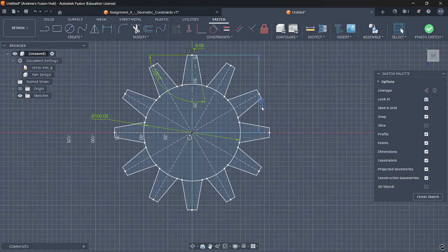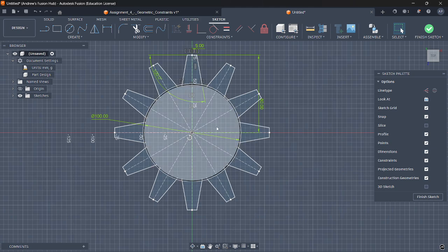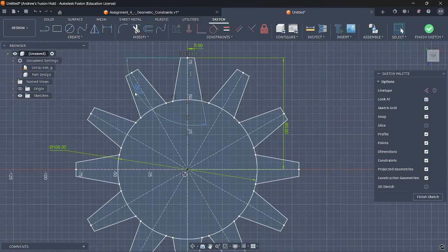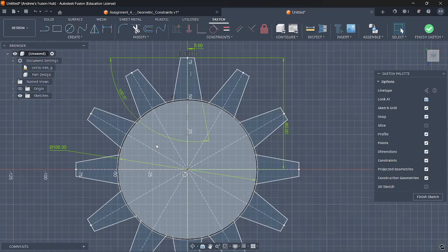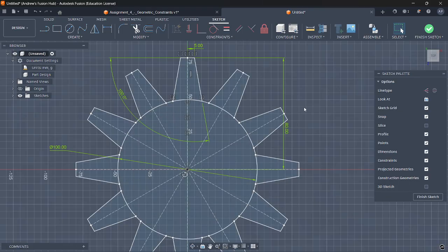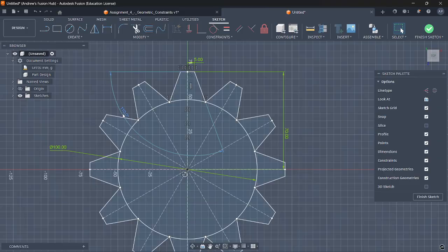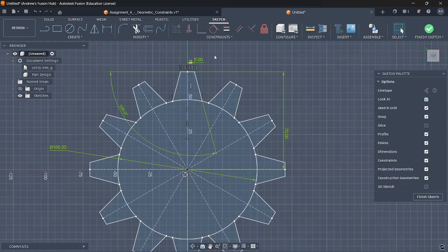That's what this circular pattern tool is, and what the mirroring does is, this half of the tooth is identical, just mirrored. So we can create a couple of dimensions here and create a more complex part that is very easy to change. I can change this angle and then all of them will go with it, which is good.